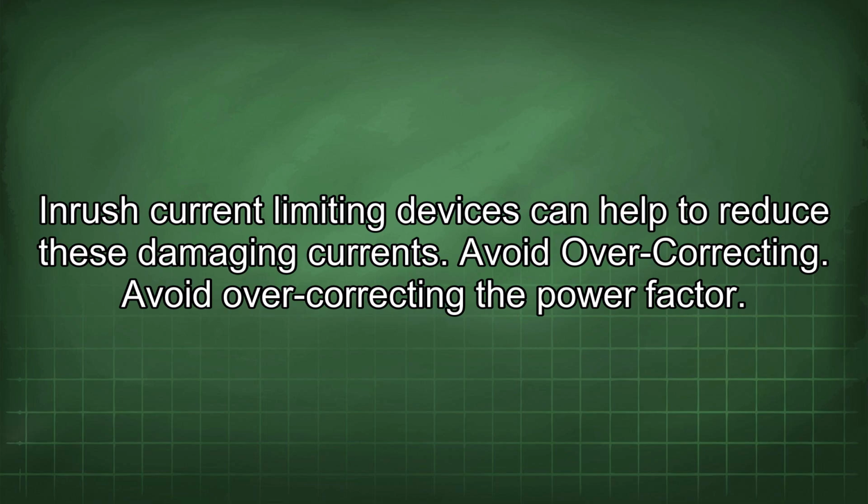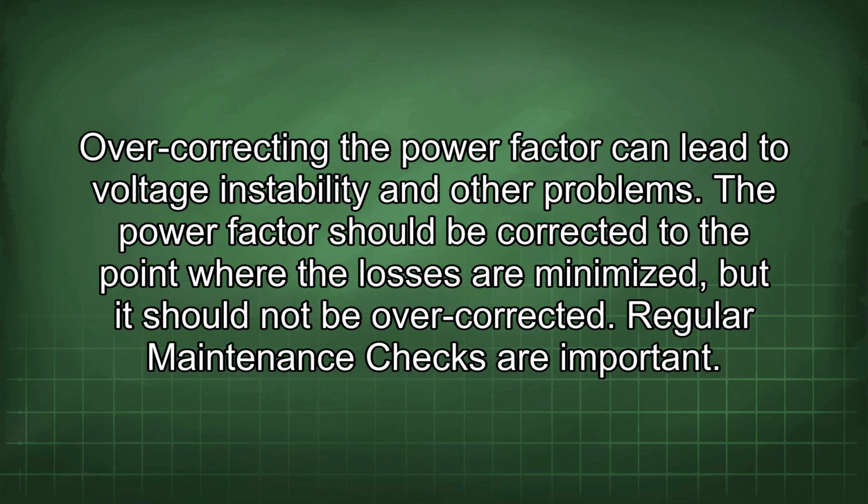Avoid overcorrecting. Avoid overcorrecting the power factor. Overcorrecting the power factor can lead to voltage instability and other problems. The power factor should be corrected to the point where the losses are minimized, but it should not be overcorrected.